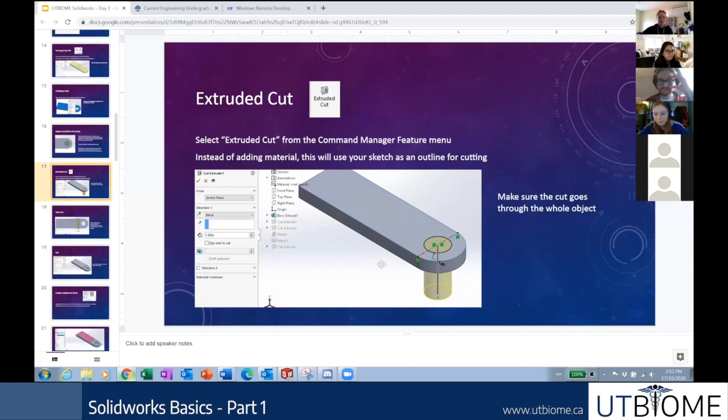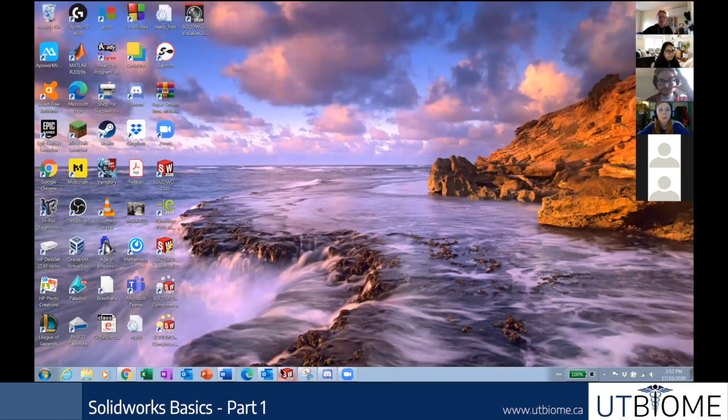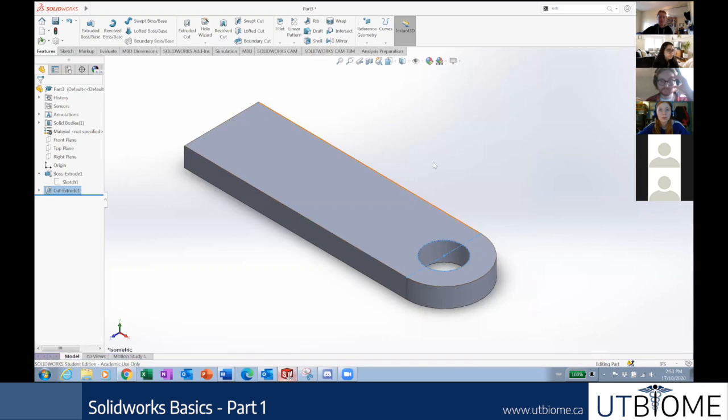Yeah, thanks for asking. So I'm just trying to put the circle on again. Okay, so I've added in that dotted line, and afterwards I have to click on the circle, and then I hold Control and bring it to the line. Is that it? So you click on the center of the circle. Yeah, like where that center point is. You hold Control, and then you left click your line, just anywhere on the line.